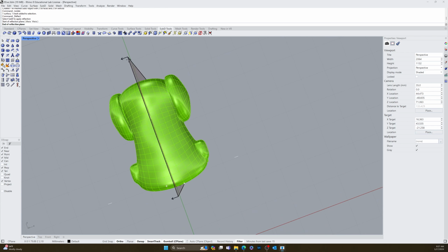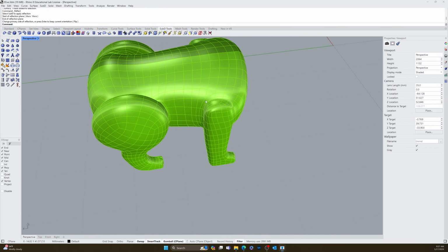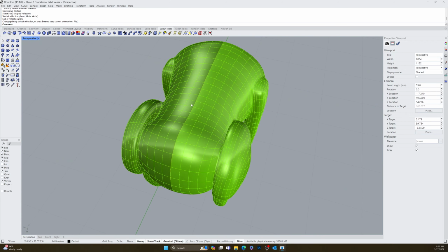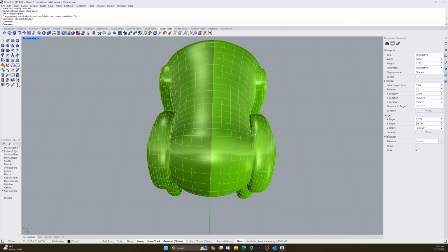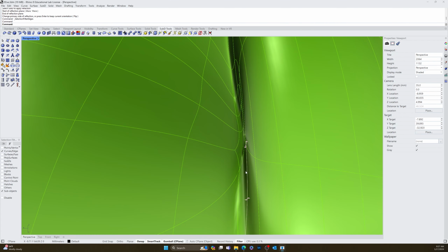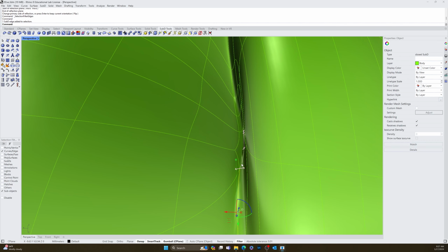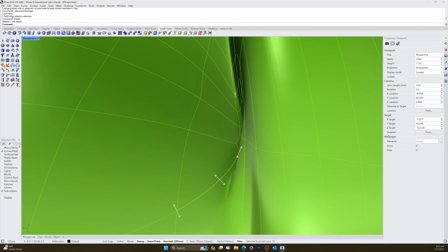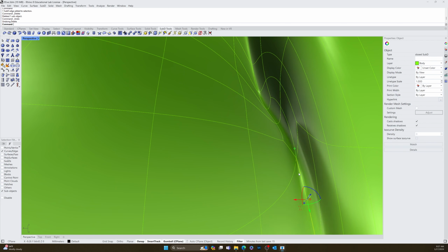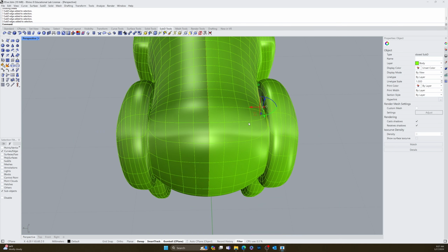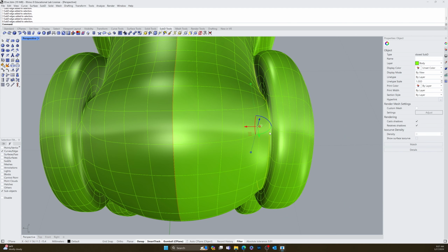Or type 0, right? Shift, click, enter. All right. So I'm going to come through here and use some edge filtering and just delete some edges because we've got too many of them, right? Like I'm going to delete. Well, I probably should have done 2 of them at a time. Delete that one, but I'm going to also shift select these kind of ones in here. Double click there, double click there, delete.